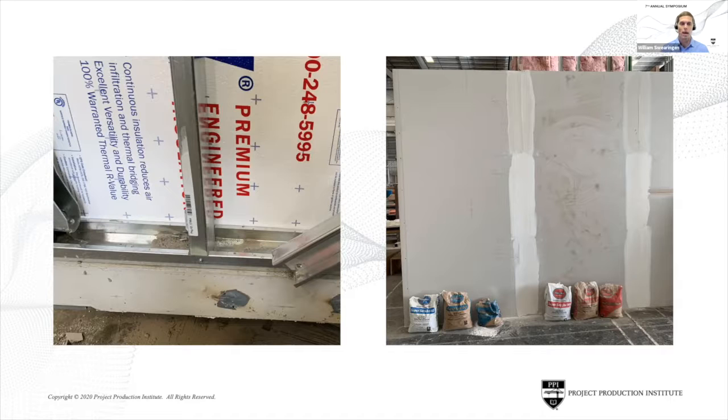So by developing a system where you can screw into the precast rather than have a hole we have to align a fastener with, we're much faster and higher quality because we're not spending time trying to align that fastener in the perfect spot.